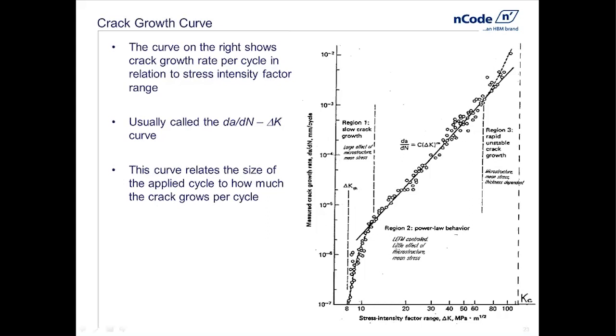We can look on this material curve and say, look across here, it says its crack is growing right now at a rate of 10 to the minus 4th millimeters per cycle. And this is a nice, what we call a stable growth region. As the crack gets longer, it tends to accelerate. This crack growth is an example of a positive feedback system, where the longer the crack is, the worse it grows, which makes it longer, which makes it worse, and so on. And it will finally fail if